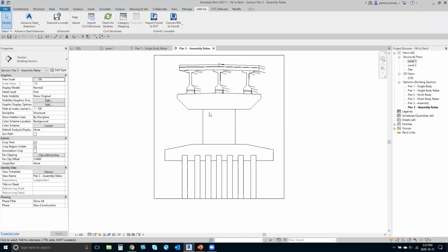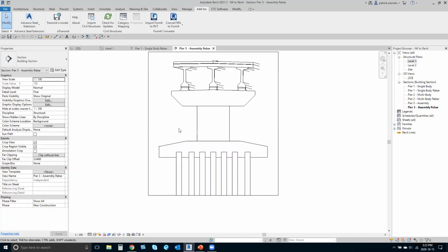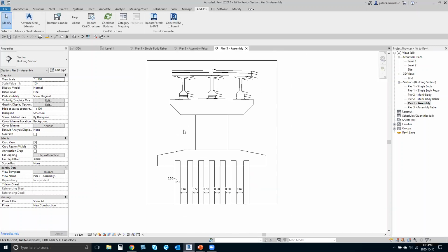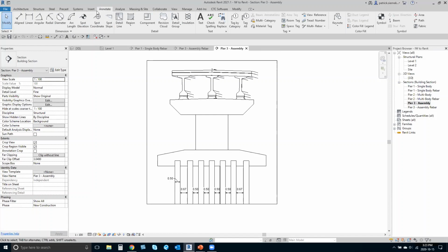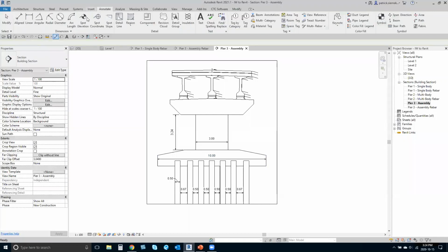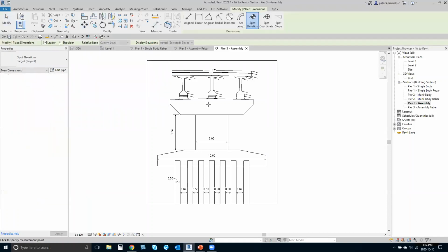First, there is extra detailing, as we have the elements as separate components, and a lot more detailing can be added. Within our detailing options, we can start to add dimensions. So inside of Revit, we have our Annotate tab, with align tools for the dimensioning, adding extra detail to our bridge design. Along with the dimension tools, we have spot elevations, which are crucial with bridge design since we definitely need to know where all the different values of the levels and elevations of the bridge itself are.